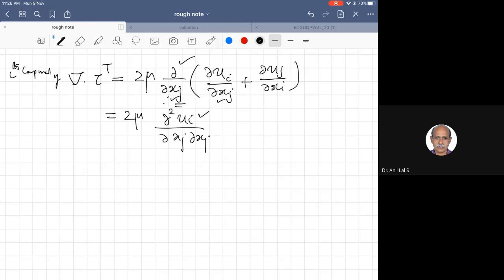The ith component of u, second derivative of the ith component. Actually, ∂²ui/∂x1² plus ∂²ui/∂x2² plus ∂²ui/∂x3². So j will be varied and summation is done. Plus here there is an xj. So ∂ui/∂xj is differentiated with respect to xi, differentiated with respect to xj. So ∂/∂xj of ∂uj/∂xi.